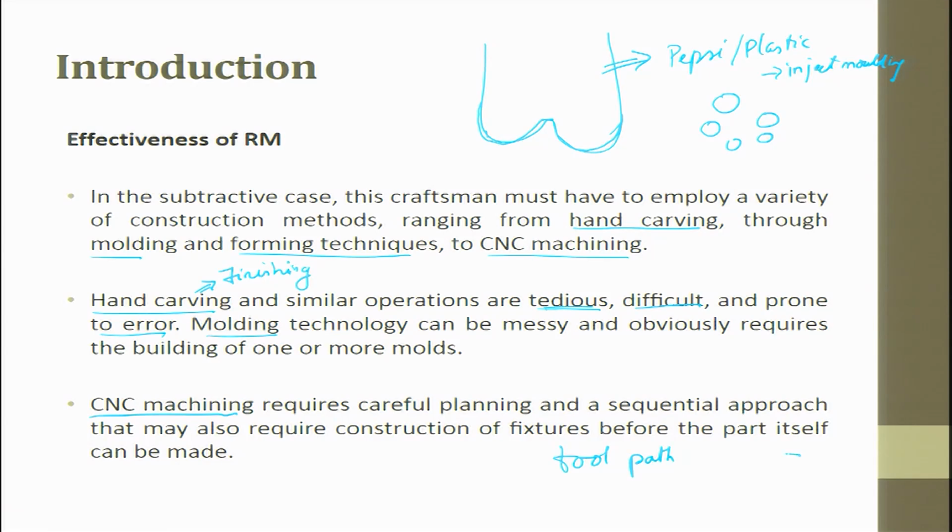For example, if you want to make a slot, and if you have an end mill of the required feature size, it is easy, right. If you have a smaller end mill, then you have to do multiple passes and try to offset the tool, to get this feature done. Exact to the feature size, it is very difficult to make tools. So, you use standard tools, have optimized tool paths, and then start machining it.